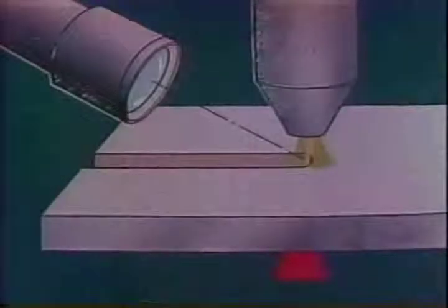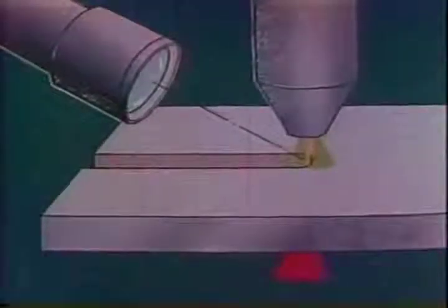The behavior of the front wall in laser gas cutting is also of substantial importance. So let's observe with a high-speed camera the behavior of the front wall during the cutting of mild steel. In this case, the image on the film corresponds to the figure on the left. This is a typical phenomenon at a cutting speed of 1 meter per minute. The periodic fluctuation of the reaction zone and melt flow is observed distinctly.